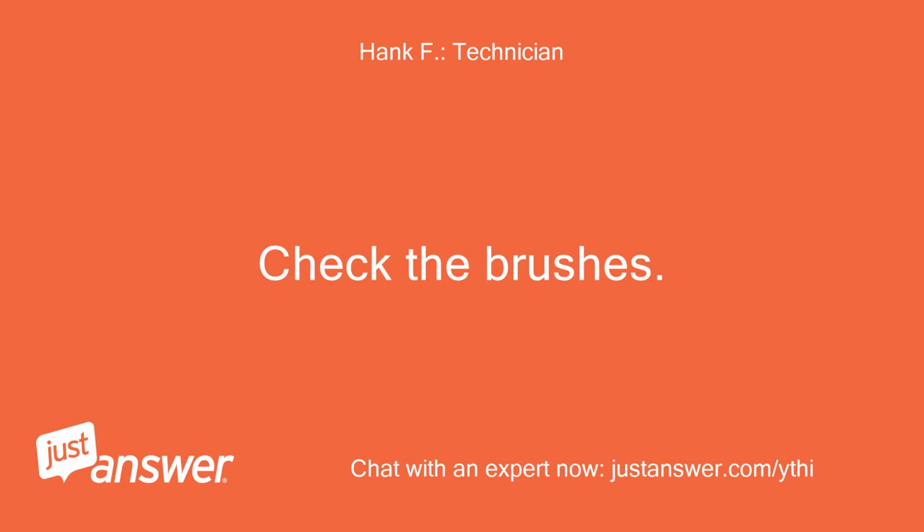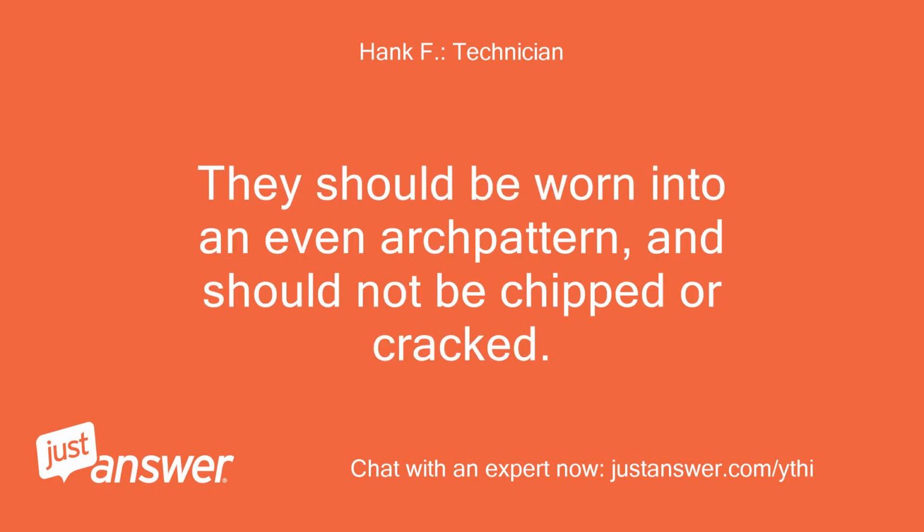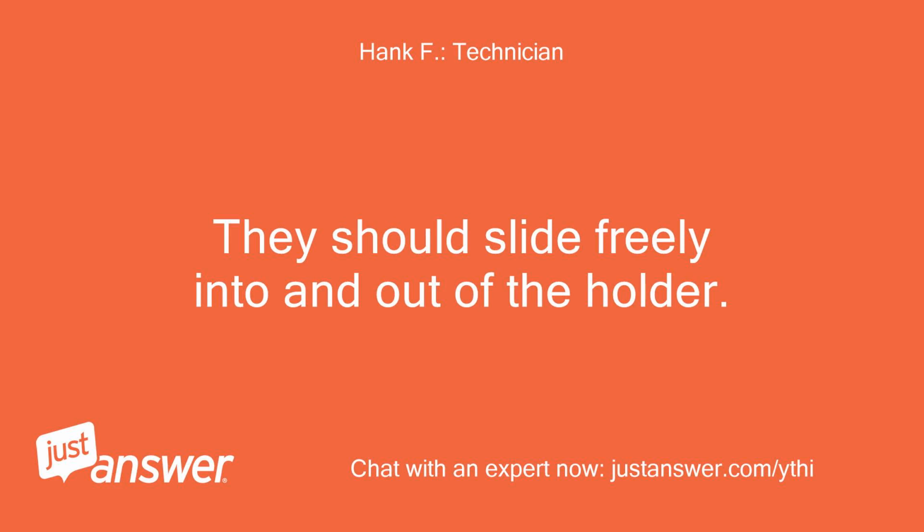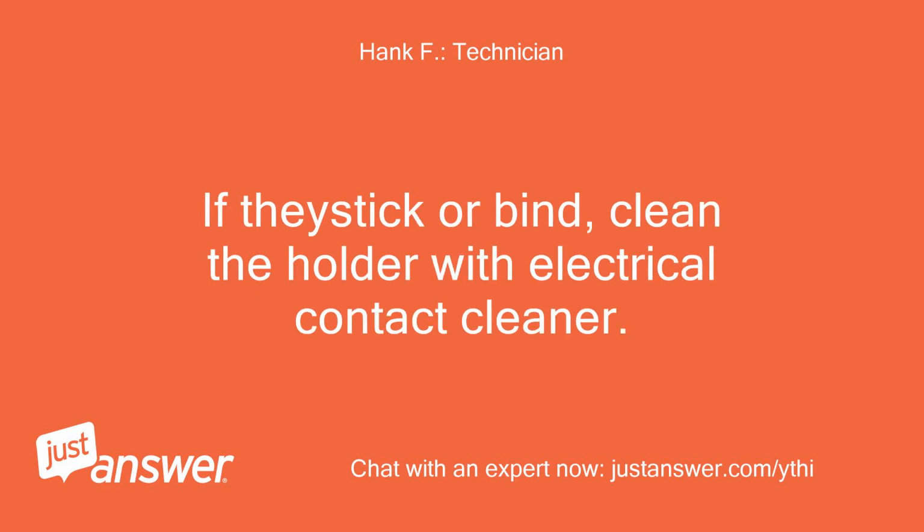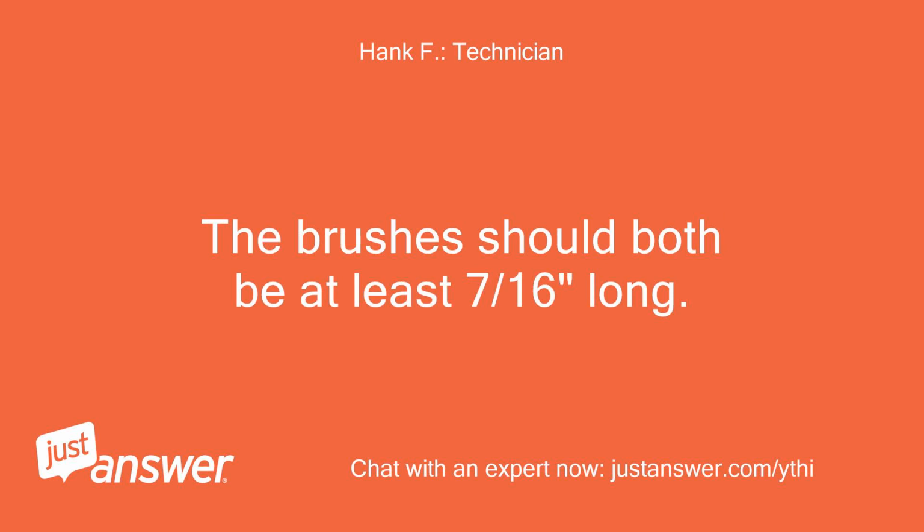Check the brushes. They should be worn into an even arch pattern, and should not be chipped or cracked. They should slide freely into and out of the holder. If they stick or bind, clean the holder with electrical contact cleaner. The brushes should both be at least 7/16 of an inch long.